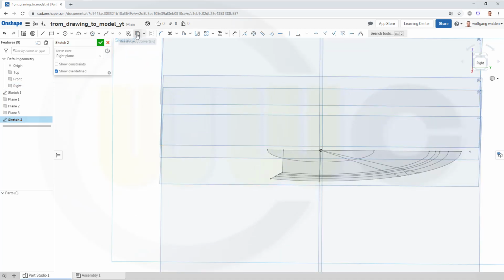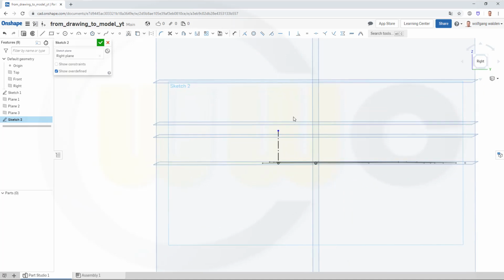I want to use this point here, so let's bring it into our sketch. Then draw a construction line here in that direction, and this should end on that plane, so go for coincident like this and draw another rectangle here, and this should be 1.5 by 2.